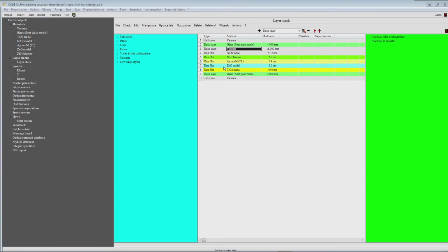But for the thermal properties of the glazing, that means the U value and also the G value, it makes a difference what kind of properties we have here in this gap, especially the viscosity and the thermal conductivity and so on. And so we need realistic gas values there. And we can do that in the following way.